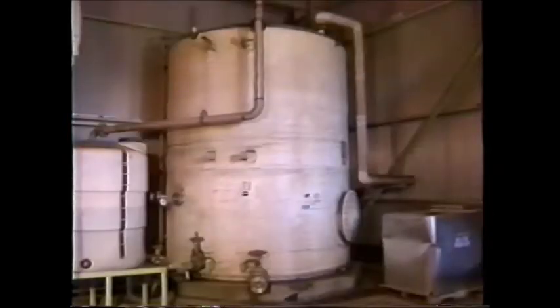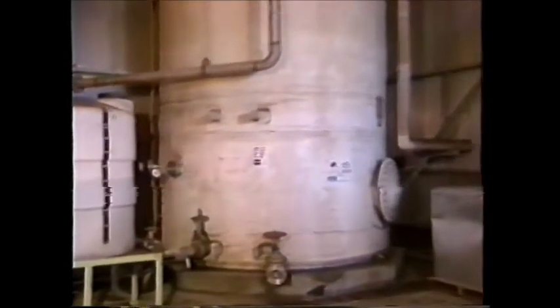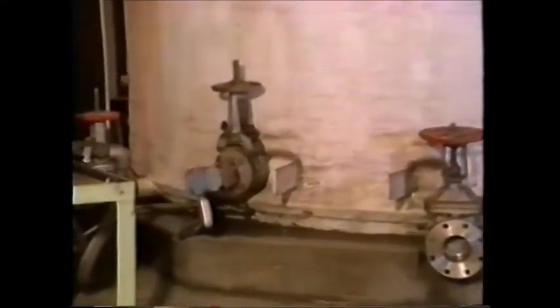You'll recall from our earlier discussions that there is a direct relationship between the height of a fluid and the pressure it exerts on the bottom of its container. This tank is partially filled with fluid. A transmitter senses pressure at the bottom of the tank and produces a signal proportional to the pressure. The instrumentation system then compensates for the density of the fluid and generates a signal proportional to the tank level. Such a system would not be accurate on a closed tank which is pressurized.